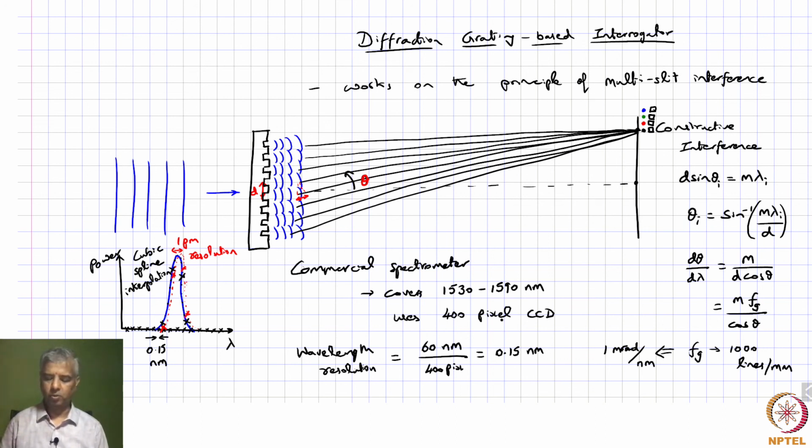So if you have 400 pixels, it has to read 1 pixel at a time, and then come back and read the next one and so on. So to read 400 pixels, typically the rate at which you can read this is in the order of tens or hundreds of kilohertz at the best case.